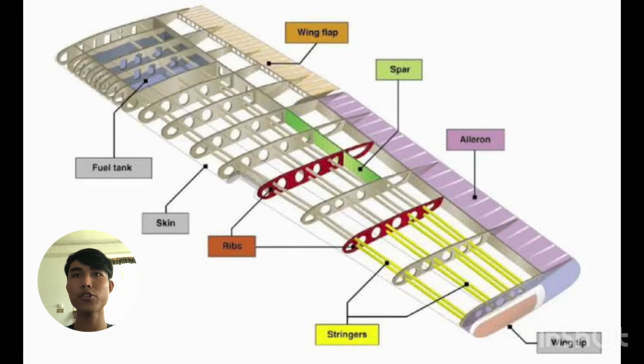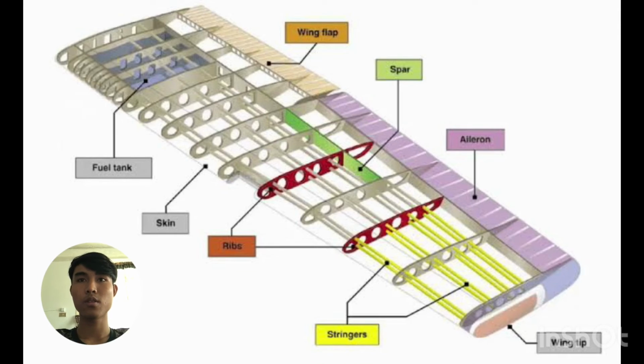The principal structural parts of the wings are spars, ribs, and stringers. Ribs. Wing ribs determine the shape and thickness of the wing. Spar. The spar carries flight loads and the weight of the wings while on the ground. Stringers run spanwise and attach between the ribs. Their purpose is to serve as structural components that transfer loads and stress.